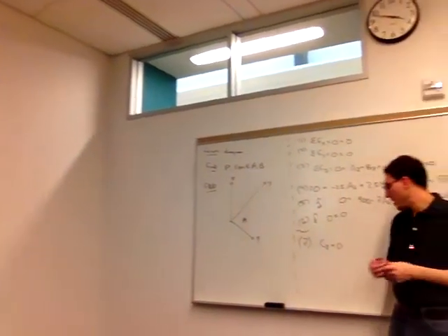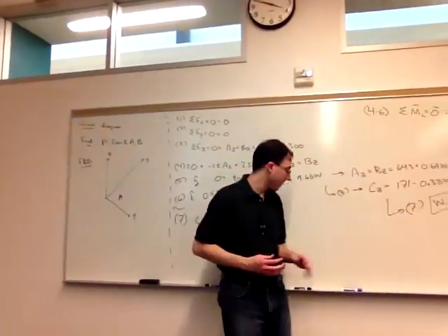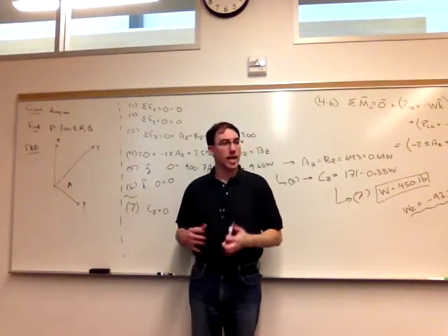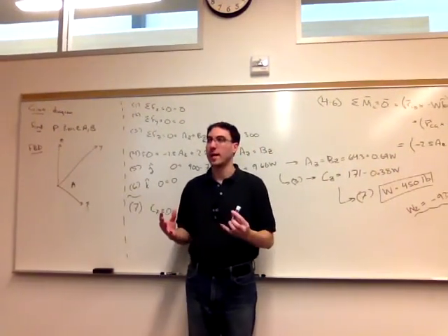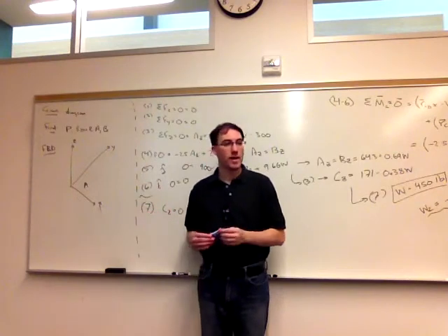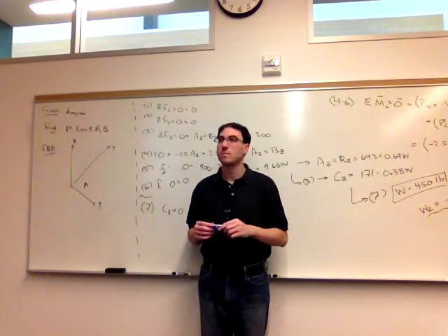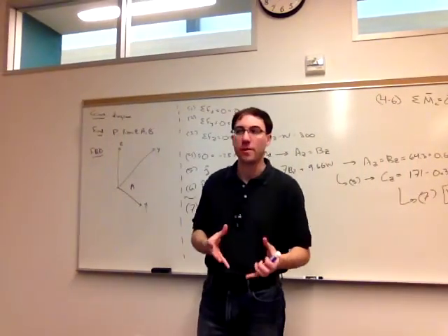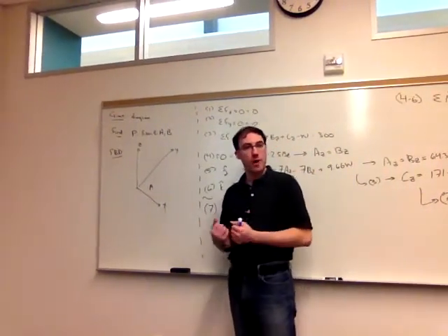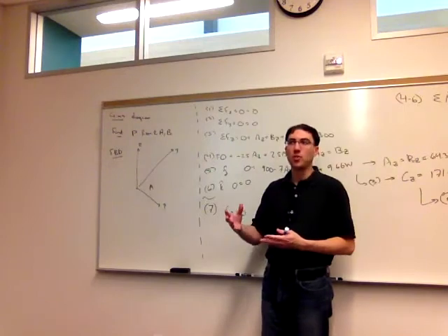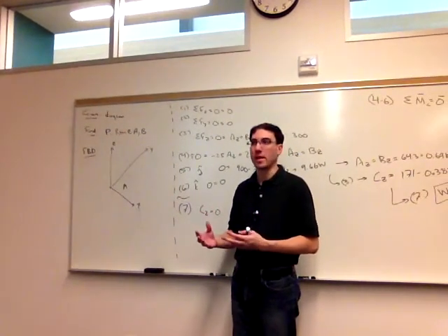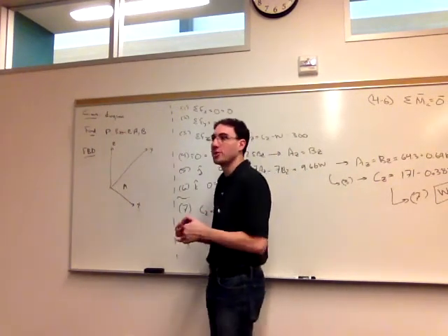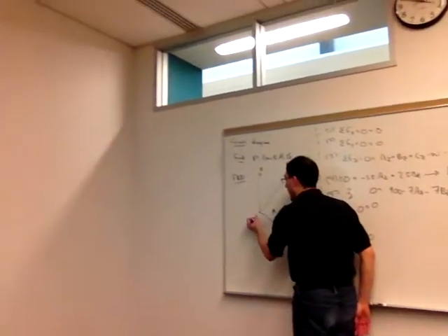So what's the object of interest here? What are we isolating from the rest of the connections, all of its connections, and representing in our free body diagram? Right, so the orange or the yellow shaft here, we're going to free it from the bearing at A, free it from the bearing at B. It'll have these two applied weights, forces on it also. So the orange shaft is what we are drawing as our object.